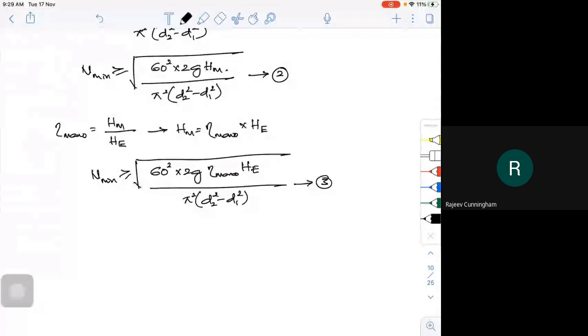So the pump has to run at this particular speed to start delivering the fluid. Otherwise, what will happen if the pump doesn't run at this speed? Suppose I substitute all the values for a given condition, and I get 120 RPM. The rated speed is 3000 RPM, but leave that, the rated speed is different. If I get 120 RPM as the minimum starting speed and the pump is rotating at 100 RPM, it won't deliver the fluid.